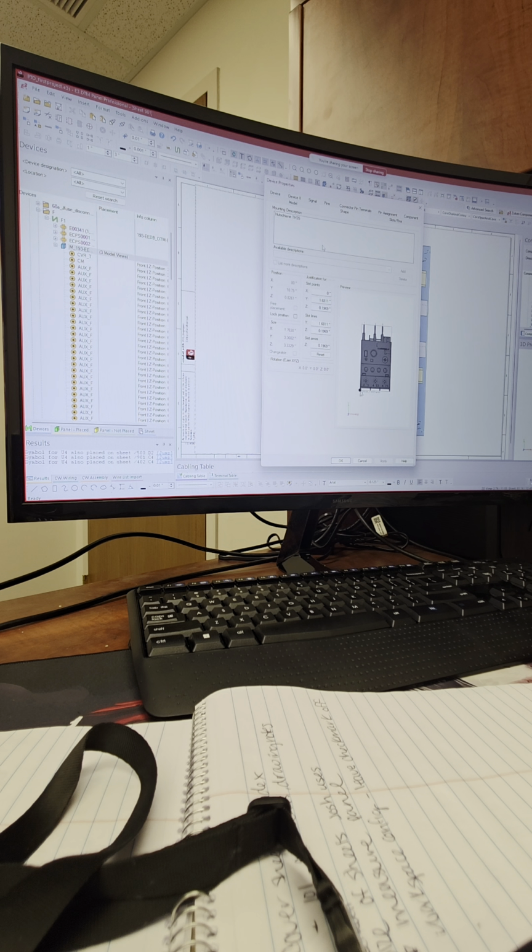Now, considering component cloud is for the whole planet, they have parts that are, let's say, German native parts. So when they do their mounting description, as we call ours TS35mm, their mounting description, as you see it on your top left, in German says Hutschiene, TH35. So that mounting description, while correct, is not in the proper language. This CLX tool itself has a mapping feature, just like any other mapping, to say, okay, if you run into library Hutschiene TH35, convert it to TS35mm, the one that you expect to see here. That's something we can do from the support side to help you with that mapping aspect of it.